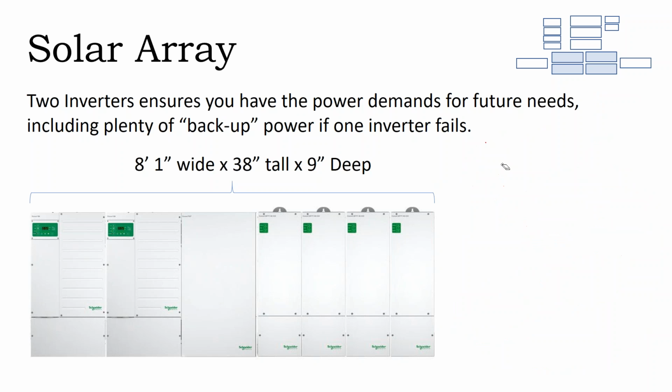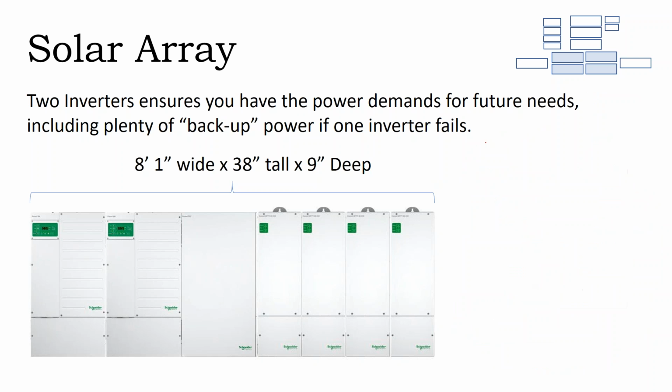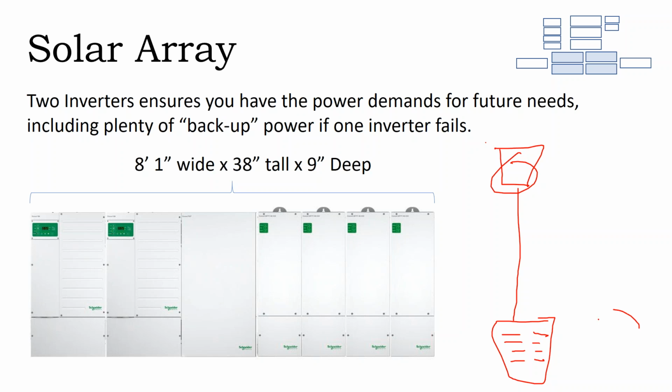Erase this. And so what we have is your meter, and then your electric service panel. And for residential systems in particular, it's common to take the solar array and locate it at the bottom of the bus bar. Essentially, you're feeding the panel from 2 sides, from the top and from the bottom. And you can only do that by about an additional 20%.